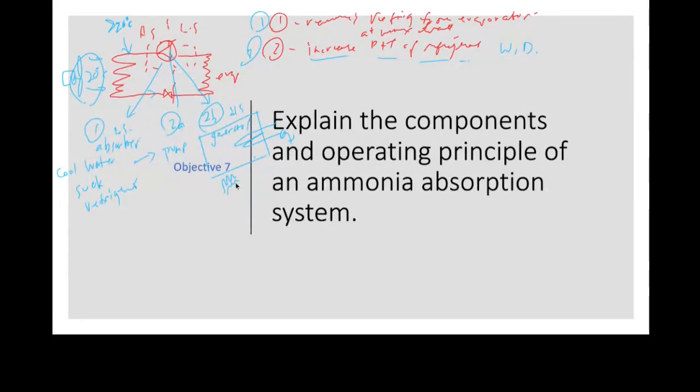Lots of different heat sources. All we need is heat. And so this liquid that we put into here, we're going to heat it up and we're going to drive off ammonia at high pressure. So what have we done then? In this system here, we are going to replace the compressor with these three components.